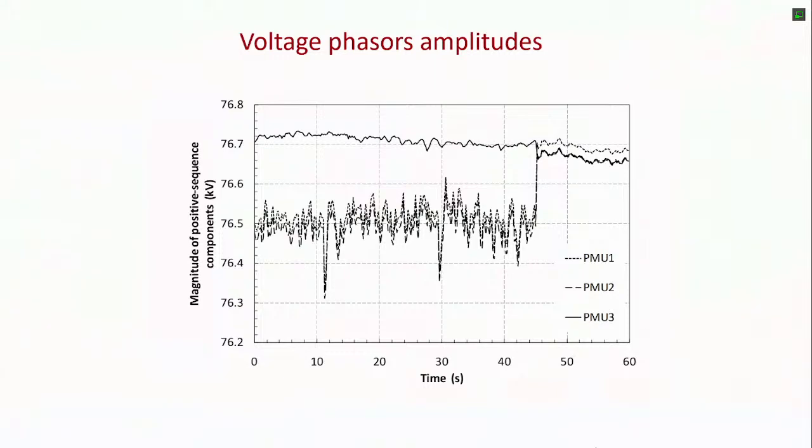In distribution networks, they are not much used. They are very common for transmission. In the transmission network, there are, I think, more than 30 or 50 stations, I mean buses of the transmission network. In particular, 400 kilovolt, particularly near the border to the other networks, are equipped with this monitoring system based on PMUs. But in distribution networks, until now, the use of PMUs is quite limited. So I'm not aware of many applications. Probably you know better.